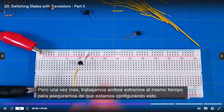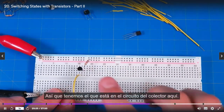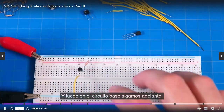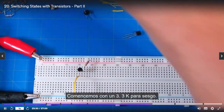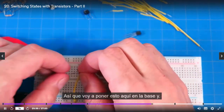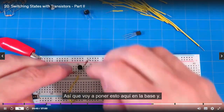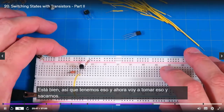But again, we kind of work both ends at the same time to make sure that we're setting this thing up. Okay, so we got the 1K in the collector circuit here. And then in the base circuit, let's start off with a 3.3K for bias. So we're going to bias with 3.3K, so that's orange, orange, red. I'm just going to put this in here to the base, and we've got that.